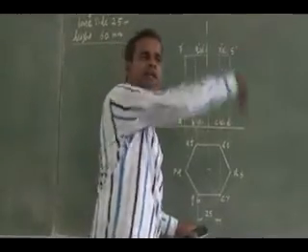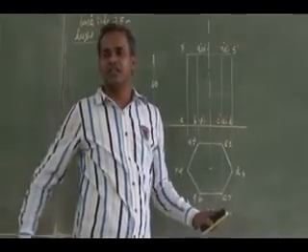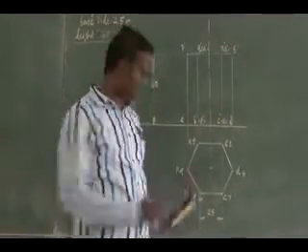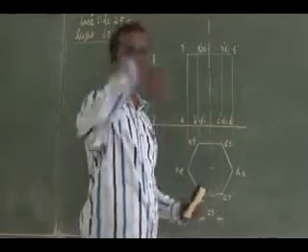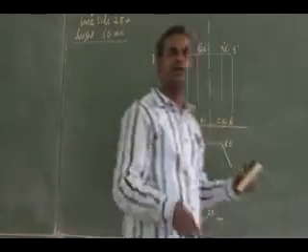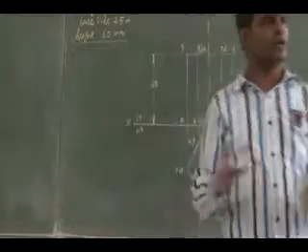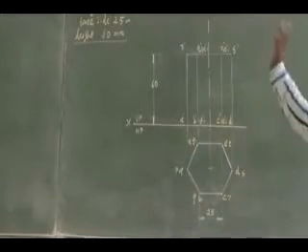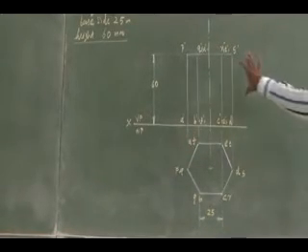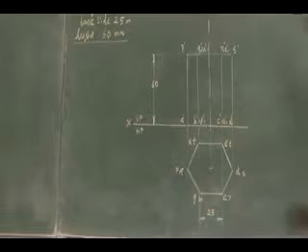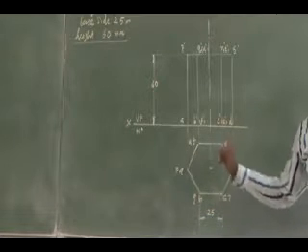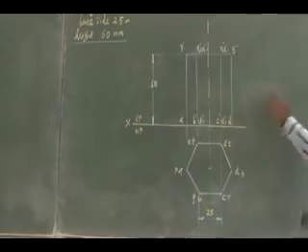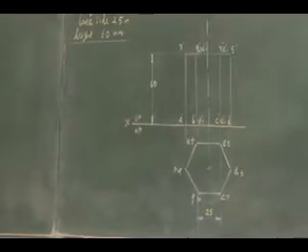What will be the height of that rectangle of my developed surface? Same height, 60. So 6 into 25 is 150 by 60, a rectangle will form. If I fold it, I will get a prism. That is the lateral surface alone. The other two bases are nothing but a hexagon, two hexagons. If I fold it, I will get the prism.